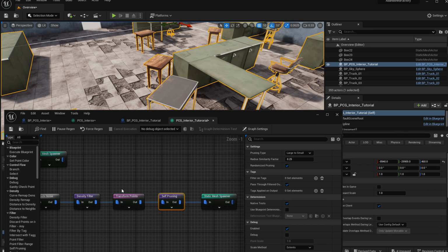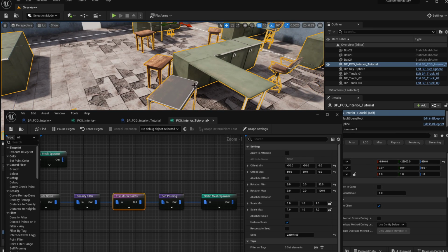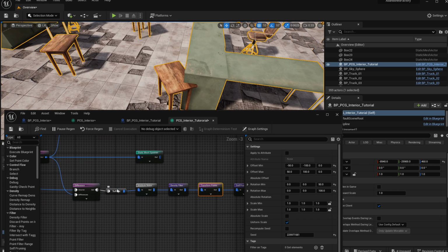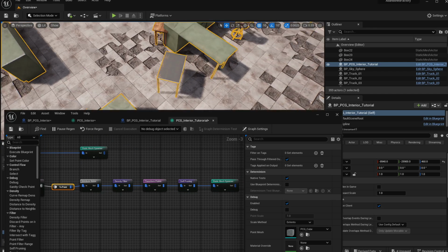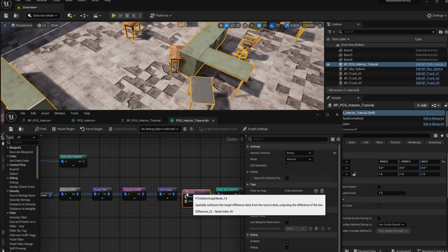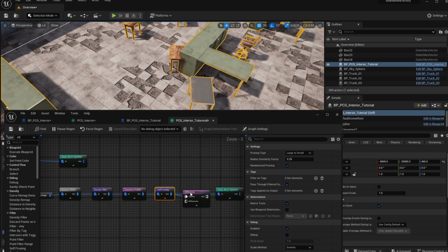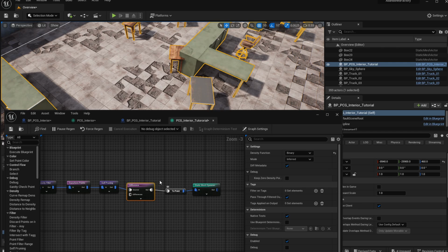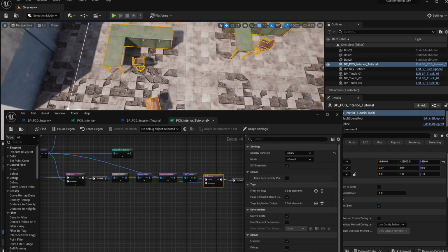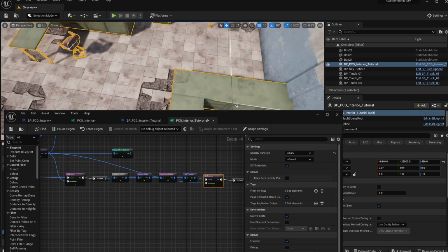Because we are randomizing the transform, you can get them to go inside the big desks. For example, if we randomize with bigger values, they're overlapping with the desks. So maybe you can do another difference here in the end. Let's copy the difference node. Let's do our final points after our transformations, and let's add into the difference the desks, the bigger desks. That way you see that no longer any table is inside of the big desk.